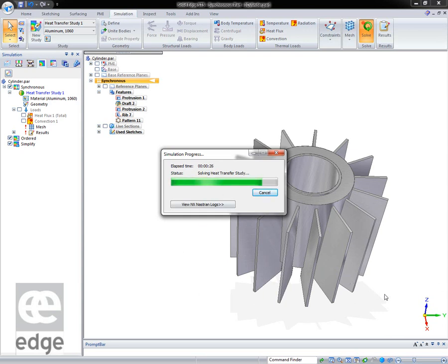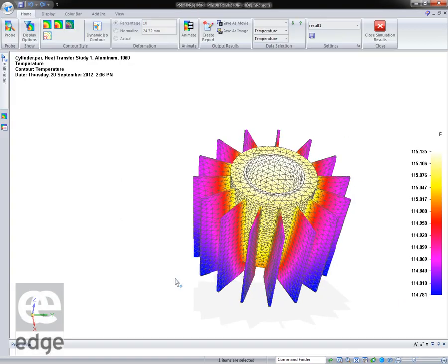So what we're doing now, as you can see, we've extended the fins, we've made the fins deeper and longer, which should help cool down the hotspot at the bottom here. And let's see what the results tell us. It's about 30 odd seconds, from memory, that it takes to process this when I put all these extra fins in. It takes a little bit longer. Makes it think a little harder.